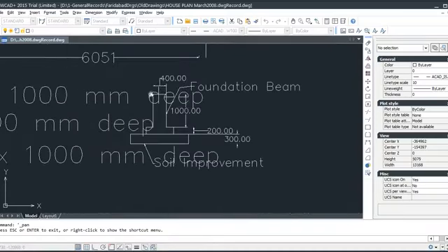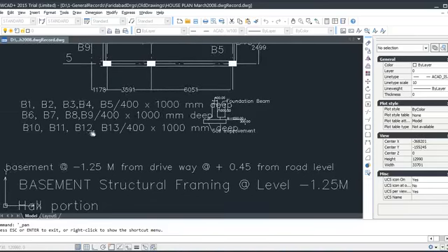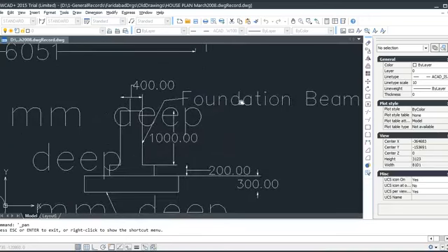This is continuous. This foundation beam. It looks like T, but it's not T beam. This is main beam, and this acts as spreader of load. And main bars are not vertical. That's for column only. For beams, horizontal bars are there. The reinforcement I've not shown, but it says B1, B2, B3, etc. All beam. This is foundation beam.